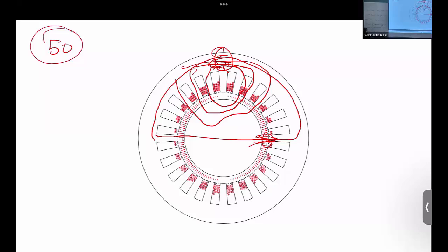So the limit of how many conductors you can put in this motor is going to be limited by how much B field is there at this point in the iron core. If the B field gets too large, then the motor goes into saturation, right? Then our motor starts to exhibit a lot of reluctance and gets into a lot of losses, because if it goes into saturation, we're doing a large BH curve. We are now in the domain of AC motors. So every time we do a cycle in our current, we are transitioning the whole BH curve, right? So we are going to have a huge amount of hysteresis losses.